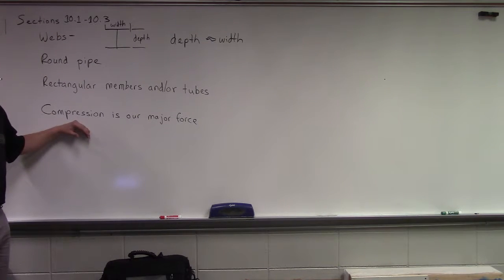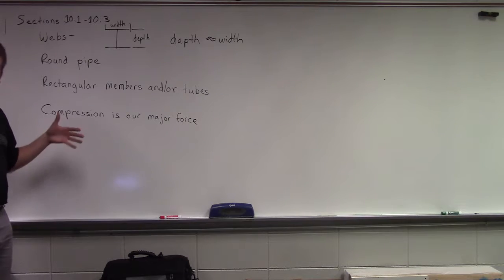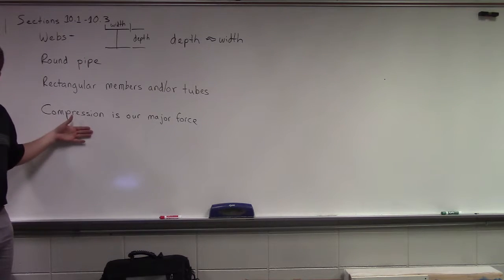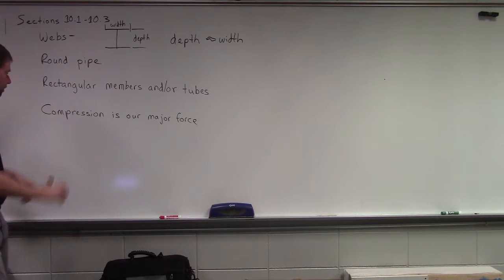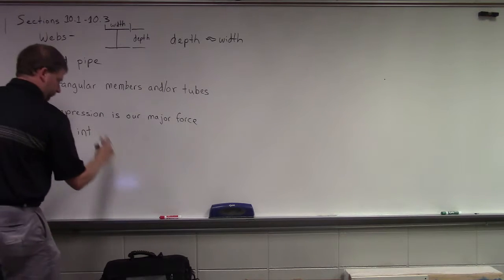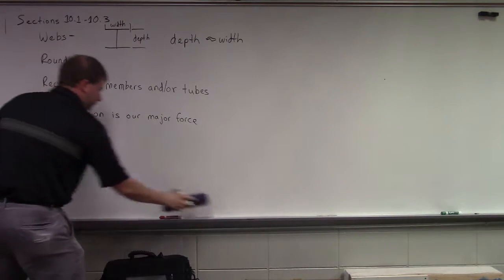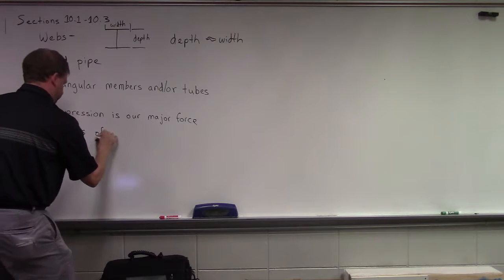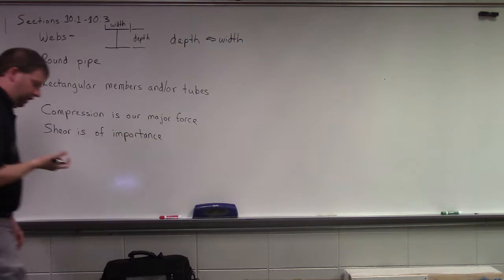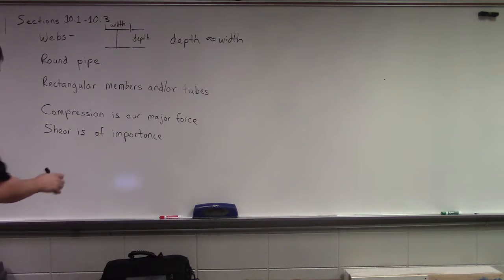But John, why did you say shear? Why do we need to be concerned about shear? The bolts. Yeah, we're going to have lateral loading going on throughout this system, right? They're going to be picking up load from floor joists. They're going to be picking up load from floor decks. There's going to be wind acting on this. There's going to be connections. So we have to take shear into account. And Rush, what did you say? Bending. Bending? Yep.